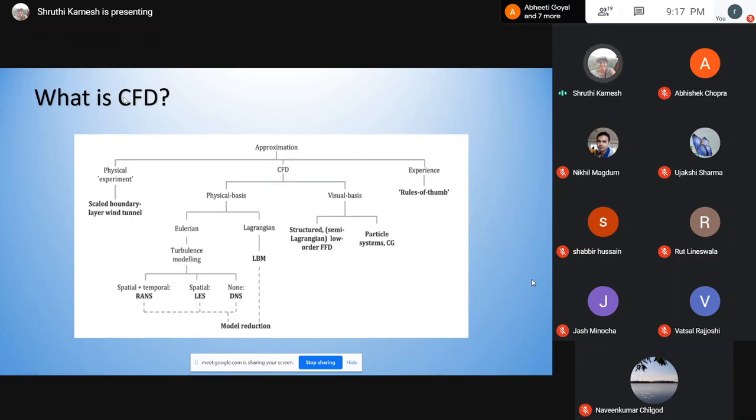Yeah, and of course, we always require physical validation where it can be done. That is for a boundary layer wind tunnel. So when you want to simulate flow through a building, for example, flow across the Burj Khalifa, that was simulated using a wind tunnel, and it has to be what we call an ABL wind tunnel. That's atmospheric boundary layer, because the entire atmosphere has a sort of boundary layer. Anyway, I will not go too much into that.